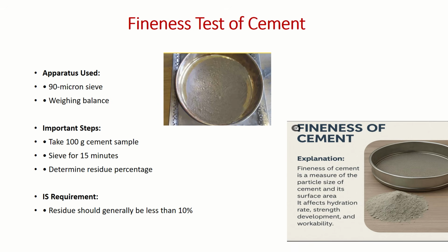The rate of the hydration process mostly depends upon the fineness of the cement. As the cement is finer, the rate of hydration will be faster because more surface area of cement is available to complete the hydration process.